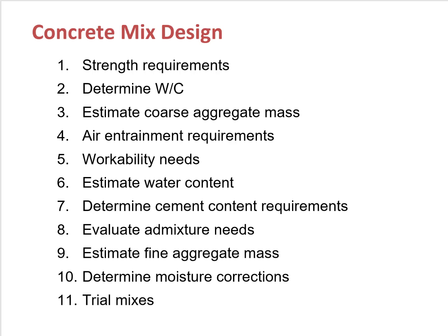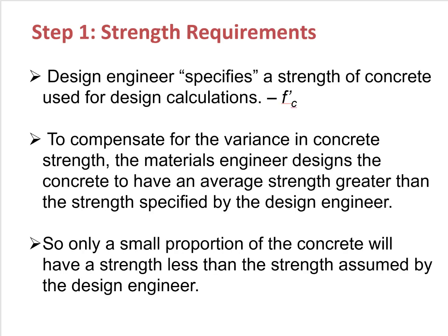And also evaluate workability of plastic concrete and estimate water content of the mix, and determine cement content requirements, evaluate whether or not we want to use admixtures, and estimate fine aggregate mass, and determine moisture corrections. In the end, we make and test trial mixes. Let's first talk about the first step, strength requirements.